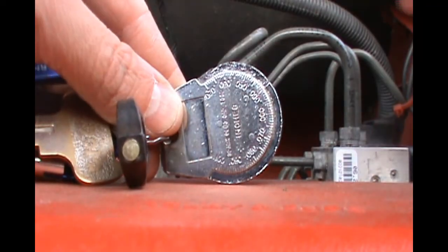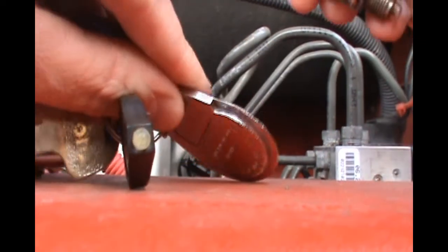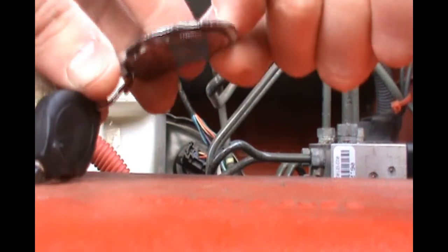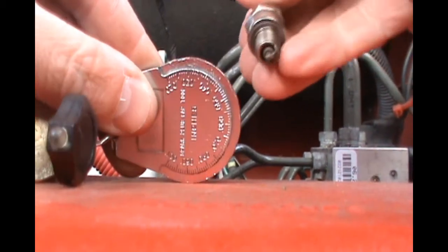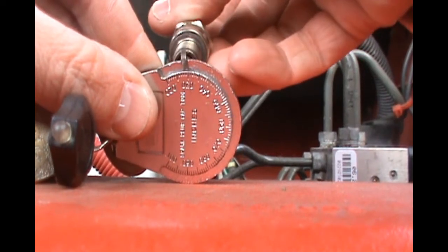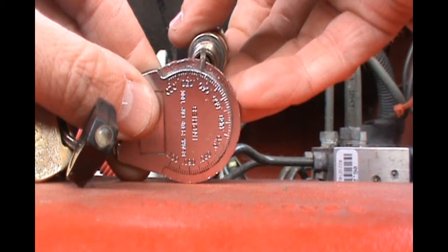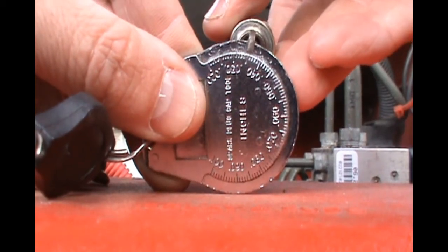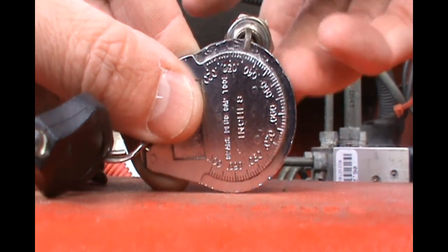In order to measure the spark plug, you have to fit the gap onto the ring of the tool. You can see the ring, as it goes around, it gets larger in width, and that is the gap of the spark plug. So I put the spark plug on here and I bring it around until it stops. And it stops right at, look close, 35 thousandths.